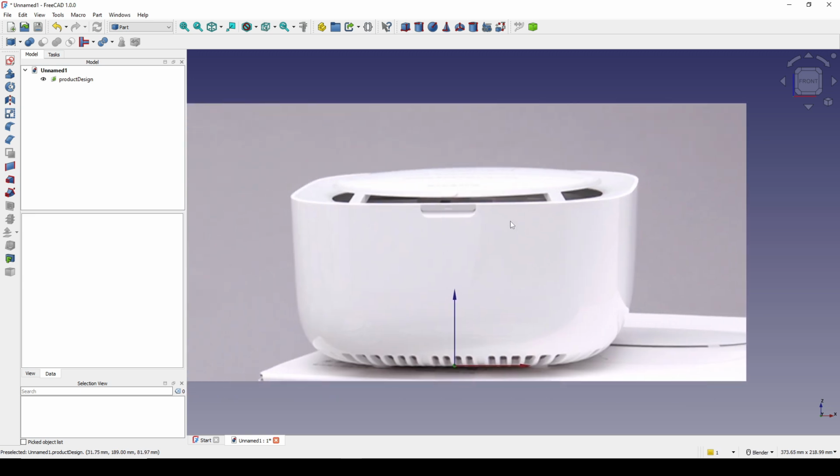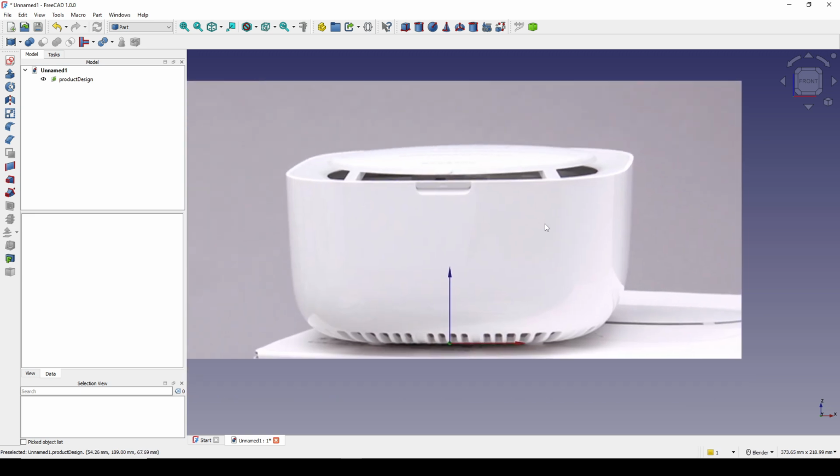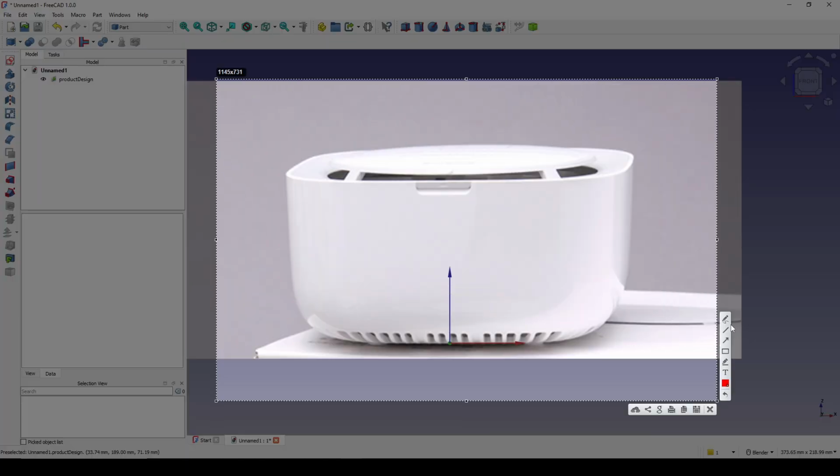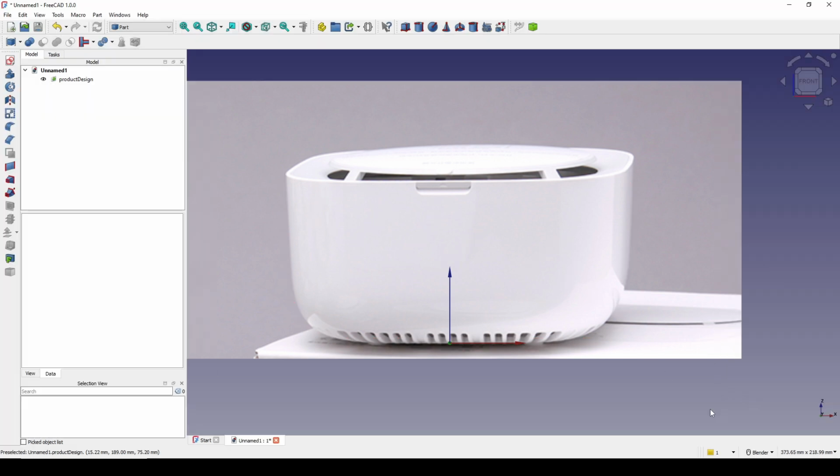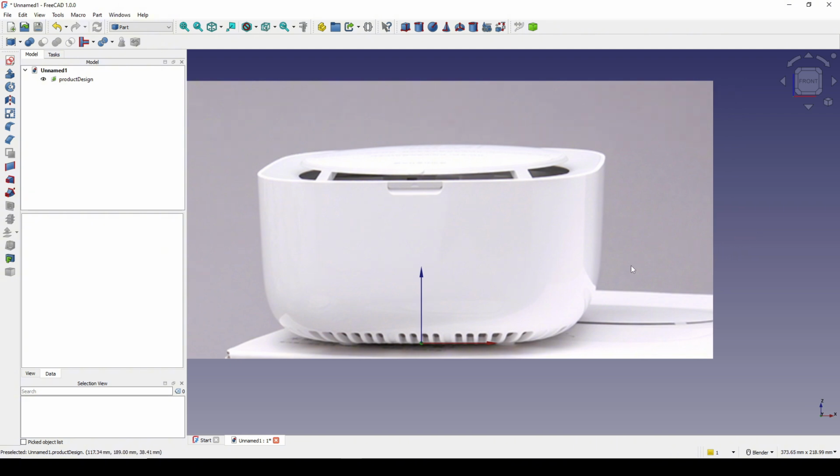Alright, so now I want to create a frame outside chasing the outline of the object. And at the bottom, I will create a round rectangle down here. And using the curve array to generate the solid in the middle. First, to change the outline, I go to create a new sketch in the front.